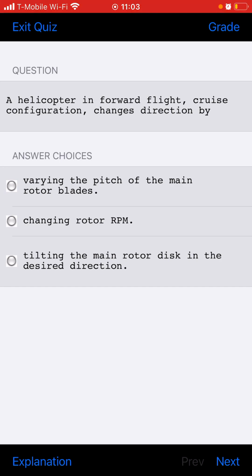Which statement concerning the 100-hour inspection of the airplane equipped with a push-pull tube type control system is true? The threaded rod end should be checked for the amount of thread engagement by means of the inspection hole provided.